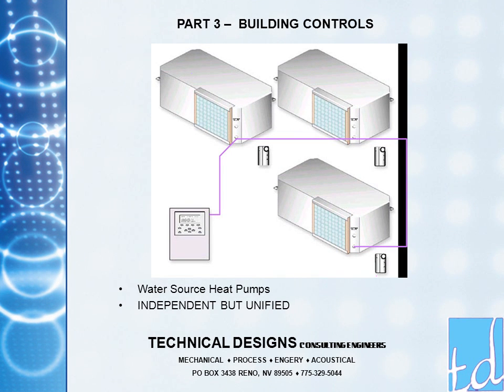We've covered the thermostats and the CO2 sensors in the space, but we have yet to discuss the overall building control system. The Fernley School has a complete BACnet-based integrated control system. Each unit operates in a standalone fashion, but communicates to the web-based front end what each unit is doing and if it's in trouble. There will be more detail on the building control system, but for now, let's look at just one or two energy saving features that occur when you have all things talking to each other.